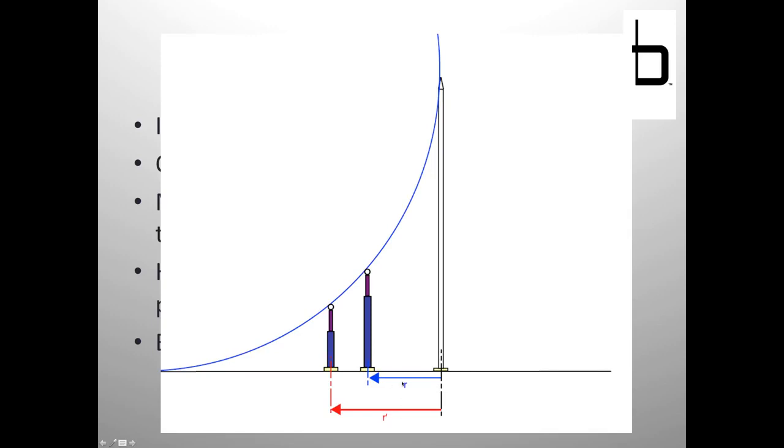We have the formulas, we have the geometry. We can calculate what this R is based on a given equipment height, and then we're given a strategy as opposed to just randomly putting masts and wires out there and seeing what we get. We can have some idea of, if I put my equipment within R, then I know I'm good.